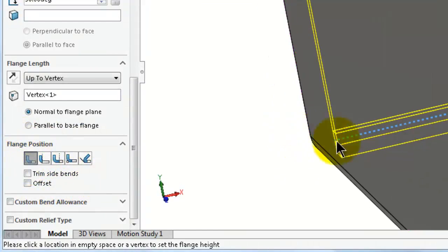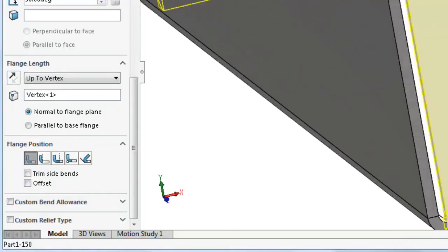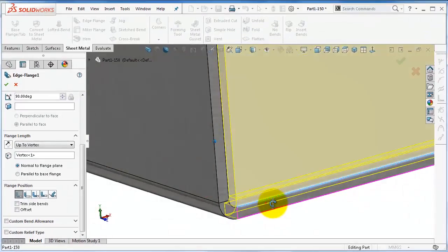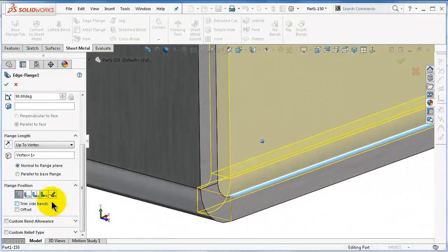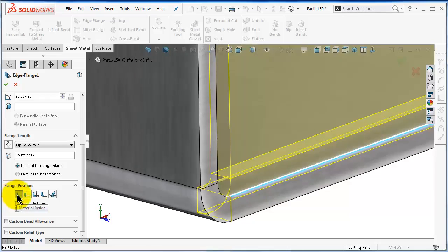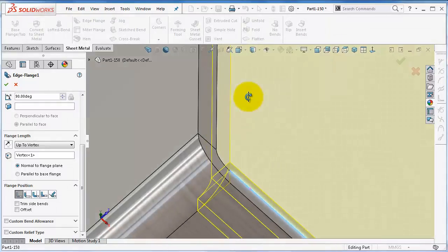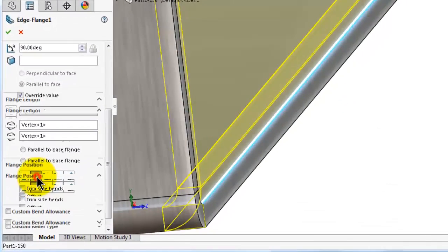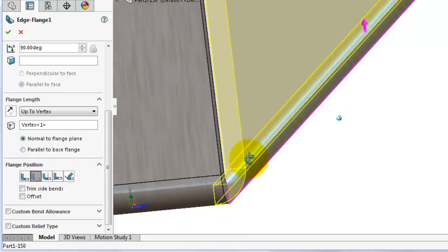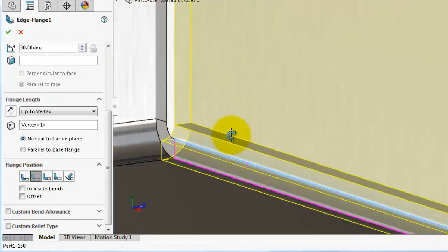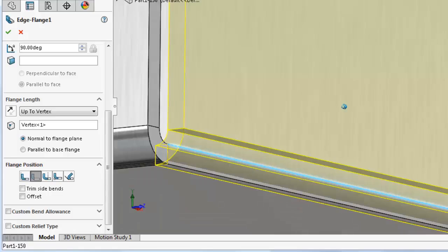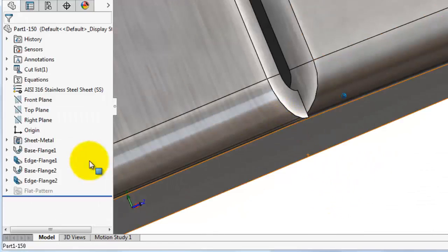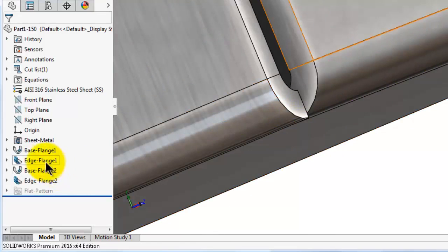The best way to understand this feature is to have a look at the shape over here. For example, we have here material inside. So in this case, the bending is inside. If you select the second option, material outside, you will notice now it looks better. Just click OK. So a better look, the bendings on the requirements.